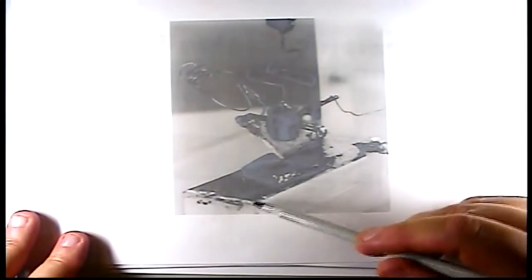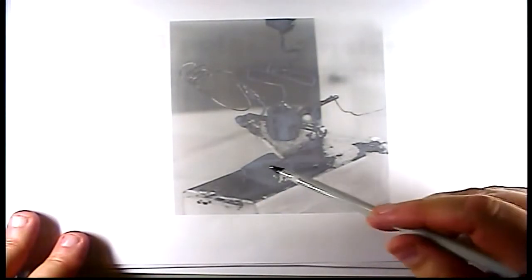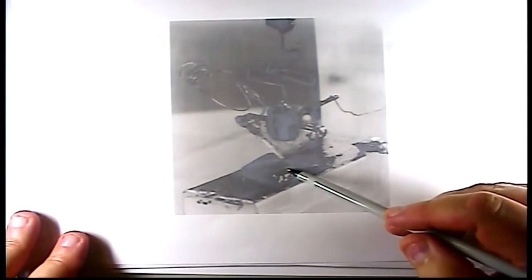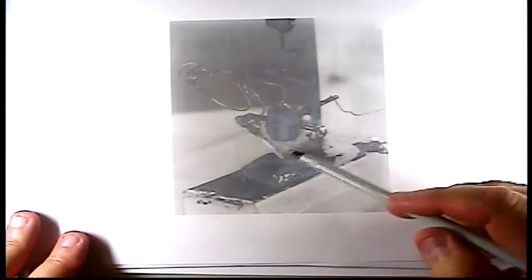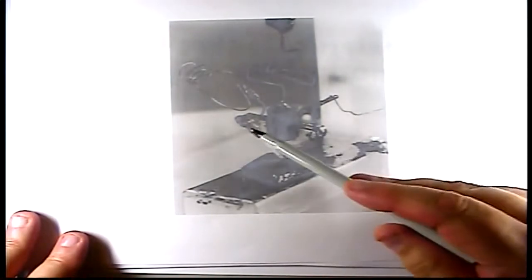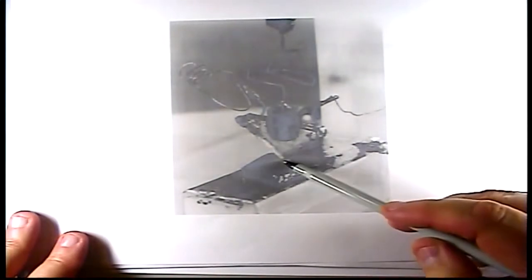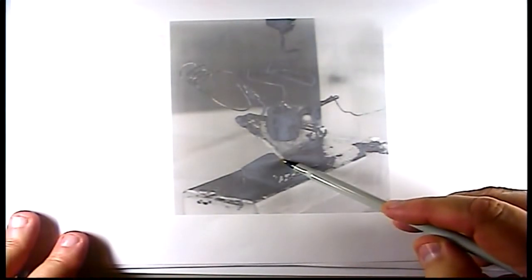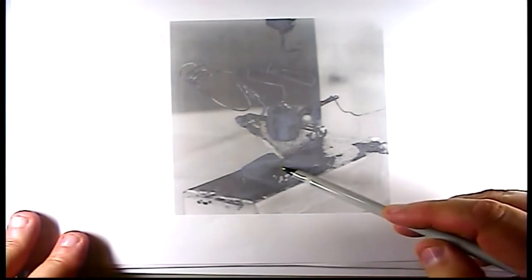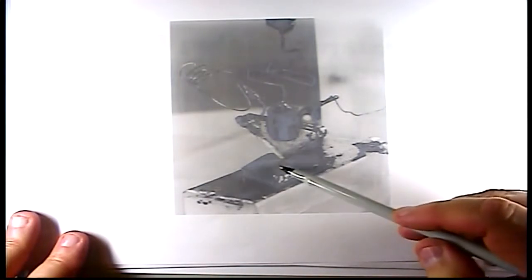You can't see this picture very well, and we're going to switch over to a better picture. But this is a picture of the first point contact transistor. What we have here is a piece of copper, and sitting on the top of the copper is a piece of germanium right here. And then there's a triangle of plastic, and down on this side is a piece of gold leaf, and on this side here is a piece of gold leaf. Down here at the very bottom of the transistor, the gold leaf has been scrubbed off in a very thin line, and that's sitting on top of the germanium.